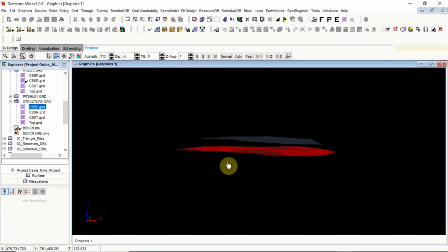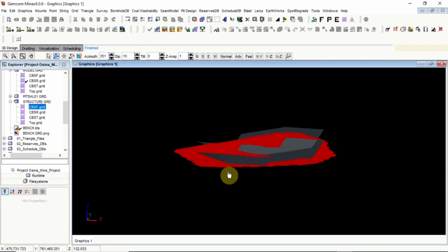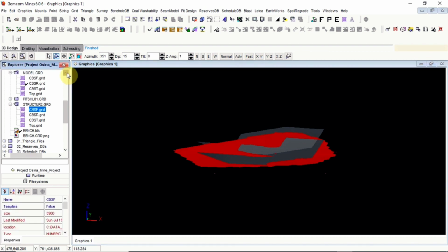Have you seen it? They are not the same thing. Do you know why? Now, in the model, the model has taken the shape of the actual crop line, subcrop line. What it means is that the model has followed a particular line to carve out the real seam floor and seam roof, unlike the other one that takes everything. Do you understand? That is the difference.